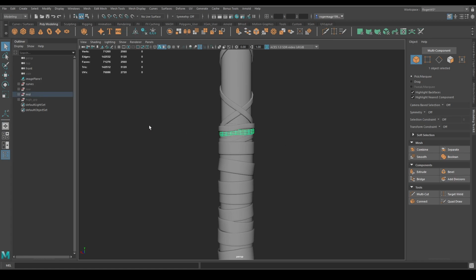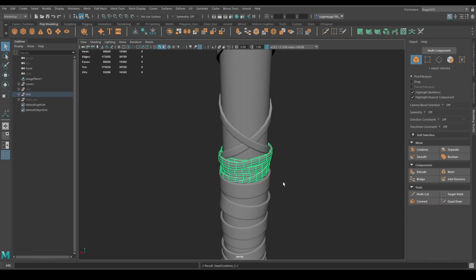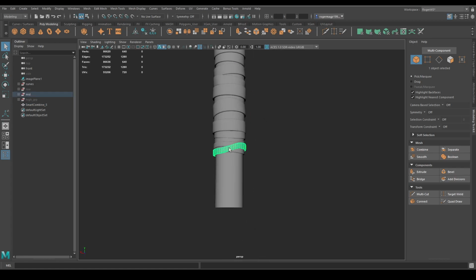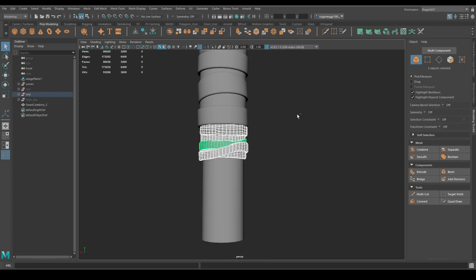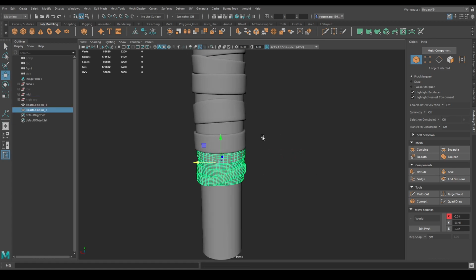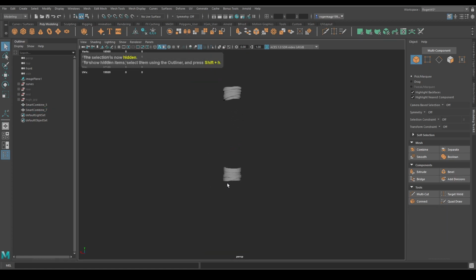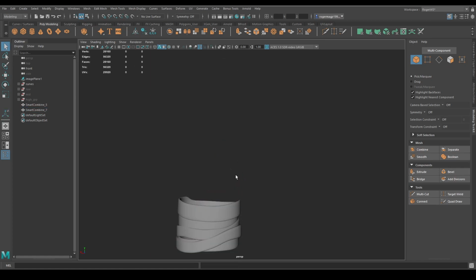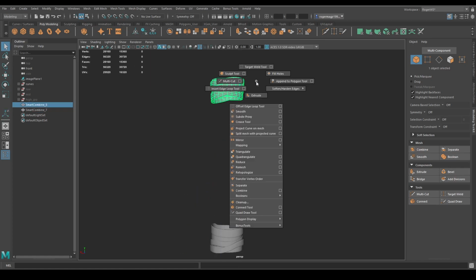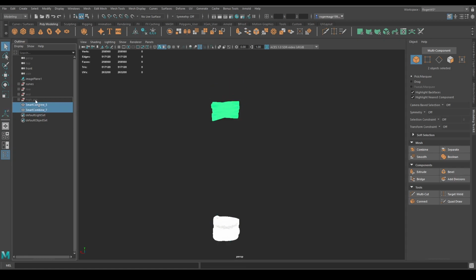Something like that. So, okay, let's do this one first. Let's combine it by clicking here and duplicate it. Shift P. This one as well. Let's duplicate it. Shift P and let's combine it. And let's hide the mid poly. Let's apply the subdivisions for this, and let's put it in the high poly.